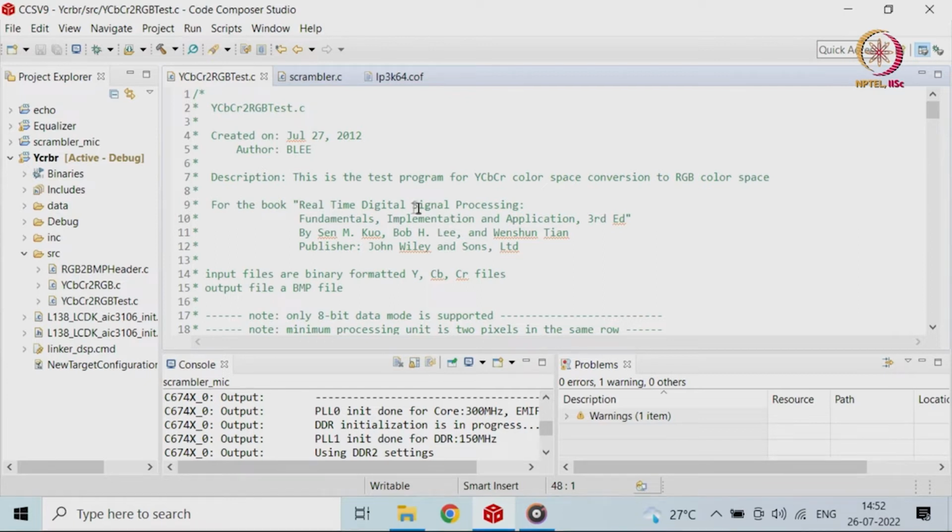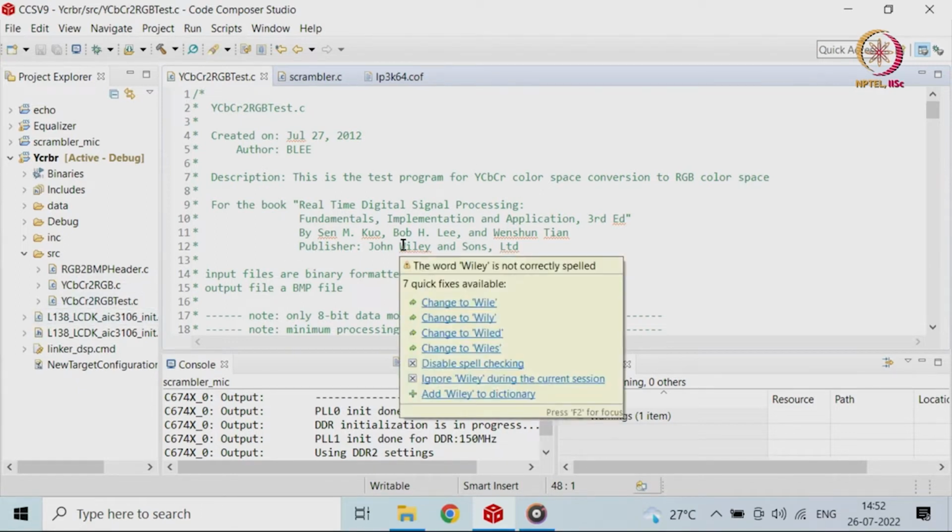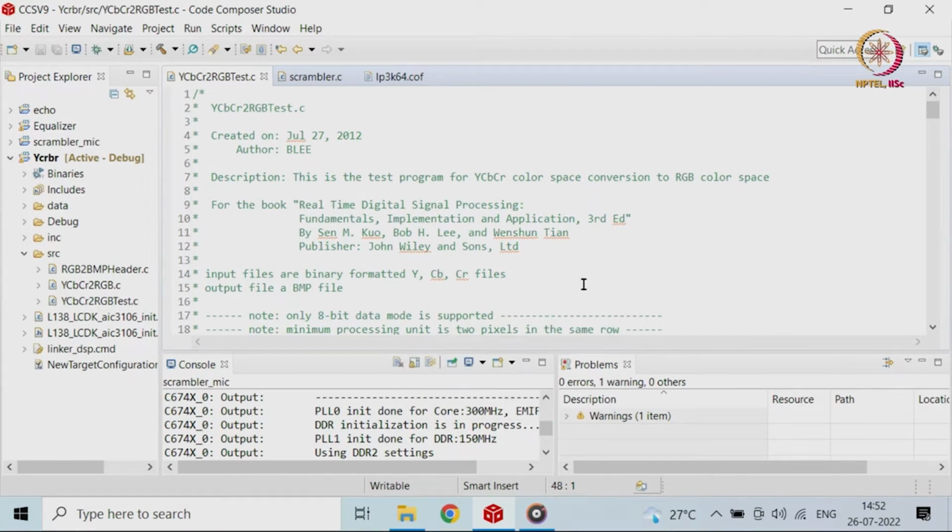If it is written in C code, you can reuse it on other boards also with little modification. In the DCT part, as we said, there was assembly code meant for this board, so to make it work on the 6x board you have to modify all the assembly instructions.